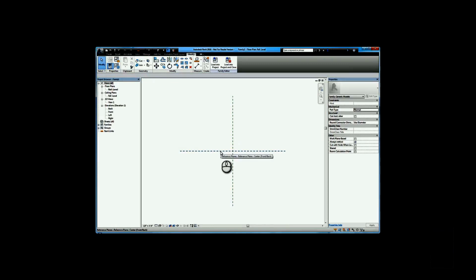These planes are long dashed lines that have 2 open circles that you visibly see when you select the reference plane. The reference planes go out to infinity to my left and to my right, or in this particular instance on the one that I selected, goes to infinity up and to infinity down. The reference plane is coming towards my face, either this one or this one.